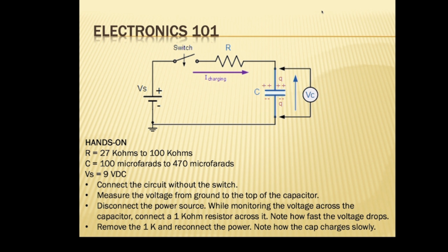If you need more than 5 connections, you just take a jumper from this row over to that one, and that gives you 4 more. So you'd have 8 places to hook up, 4 on either side, and you can daisy chain them as many as you need. To connect one breadboard to another, it's the same way, with a jumper. If we had another one sticking up here, we'd put a jumper from here up to this one, and that negative would go all the way up.